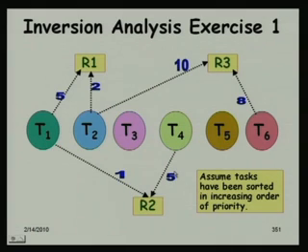What about any other? Yeah, on account of T6. T6 might be holding R3 and T2 might be requesting R1, and in that case it will undergo inversion for 8 milliseconds. What about T3? Will it undergo avoidance inversion? No, it does not need any resource. So, it cannot undergo an avoidance inversion because it will not request any resource, is it not? Only when the request for a resource is denied due to the ceiling value, it will undergo inversion.